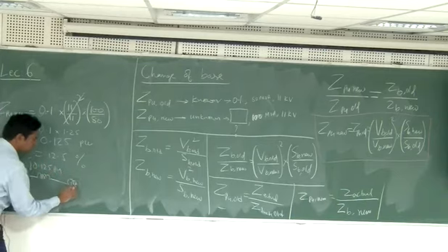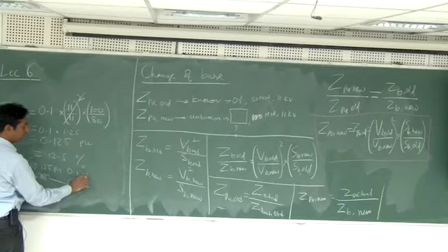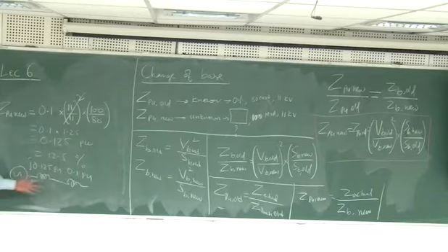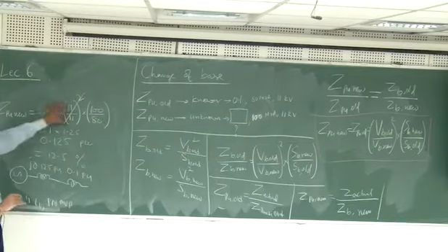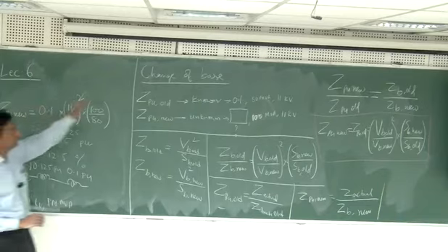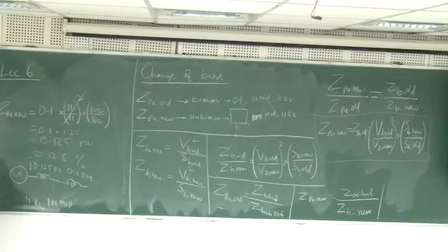And then I can put the series, I'll put the transformer 0.1 per unit. And then the entire thing is in 11 kV and 100 MVA. So this is for the entire system. This step is very important; this step is called change of base.